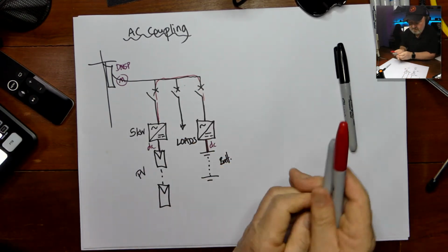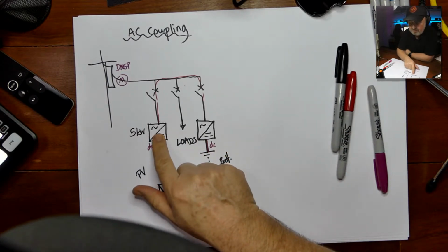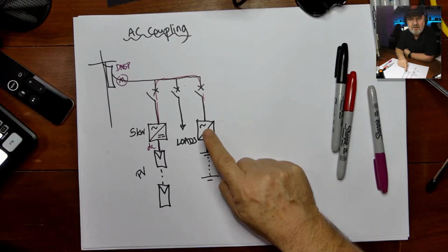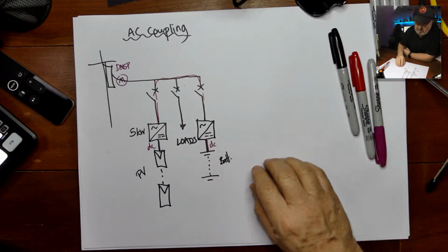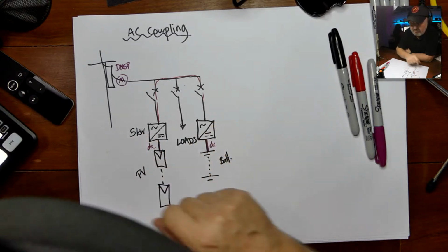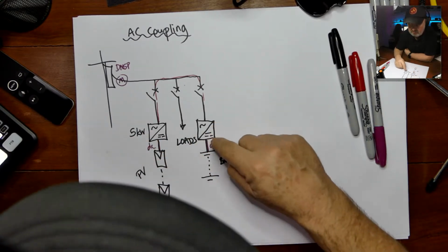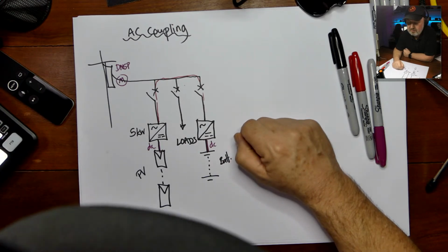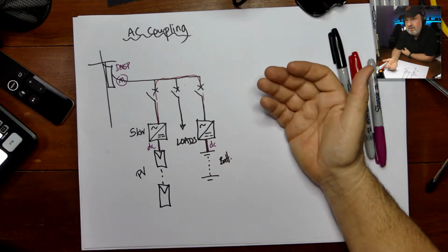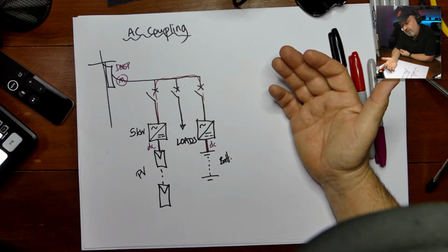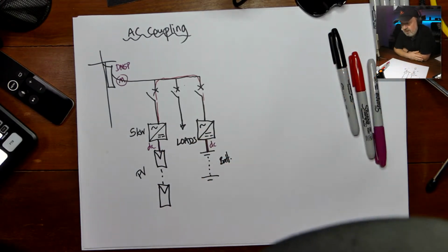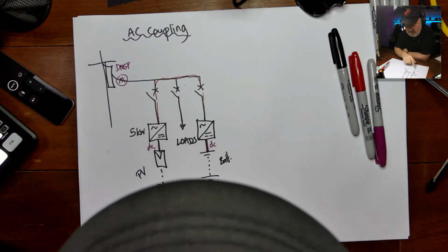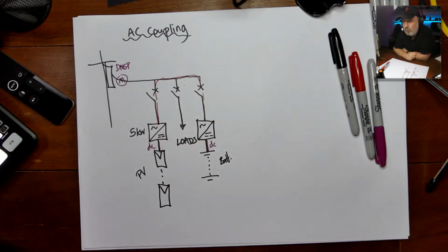But one of the advantages of this is you might notice that we had this already and we could add this later on. It didn't actually have to be installed at the same time. So that's a big plus. We could actually have multiple PV systems and multiple battery storage systems too, so they can scale up to the limits of your approval from your electricity distributor, of course, because they'll put limits on how many the inverter capacity that you can connect. Having drawn it like this, it won't work.